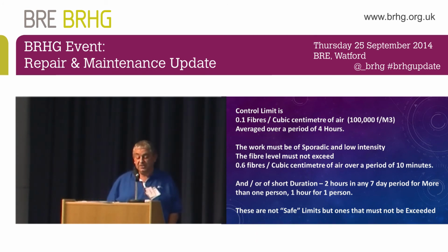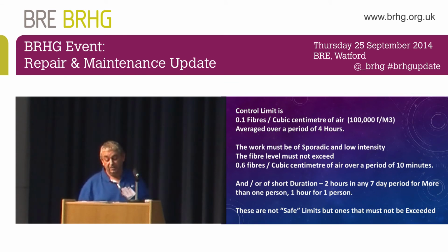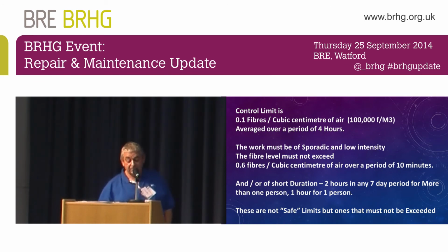And the works must be of short duration. So 2 hours in any 7-day period for more than one person, 1 hour for one person. It can be done, the regulations can be used to get quite a lot of building works done. They're not safe levels, there is no safe level, same as with ionising radiation, there's no safe level, but they're ones that mustn't be exceeded.